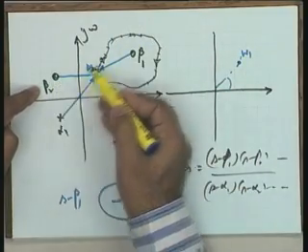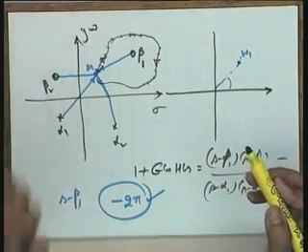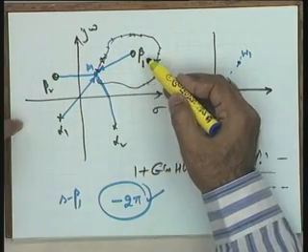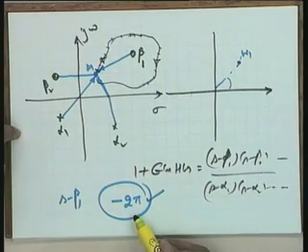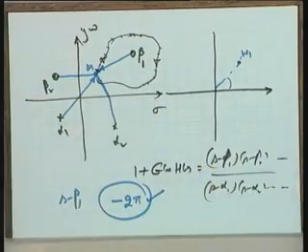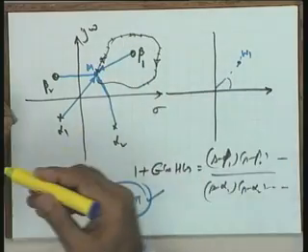So, as S traverses along this particular route, the net angle contributed by S minus beta 2, this is the crux of the total Nyquist stability criterion. If there is a 0 enclosed in it, it is going to contribute an angle of minus 2 pi, and all other pole and zero phasors outside do not contribute a net angle as far as this particular contour is concerned.